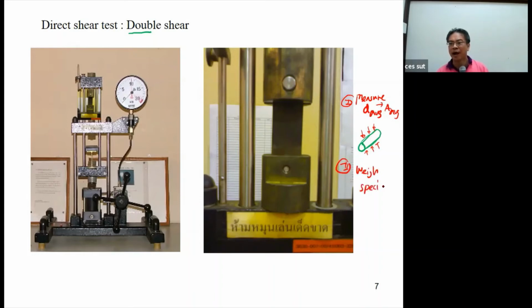And then the second one, I would like you to weigh the specimen. And when you weigh the specimen, you also need to measure the length. Okay, you just compute the density of each specimen. It must be aluminum, brass, and copper. And you just divide the weight of aluminum by the volume of aluminum. I would like you guys to determine this. This second step is the new one. We didn't do it for the previous one.